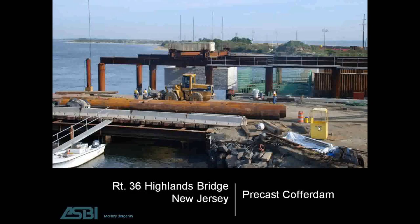I want to talk a little bit about precast cofferdams. On this project, the Route 36 Highlands Bridge in New Jersey, precast cofferdams were utilized. This is the project that I spoke of earlier that was precast from the footings up. You can see over here on the far right, the forming system is in place. The center shows the reinforcing cage being installed, and then the final section of the precast cofferdam is there ready for load out.